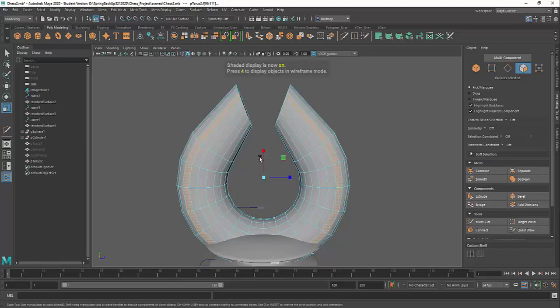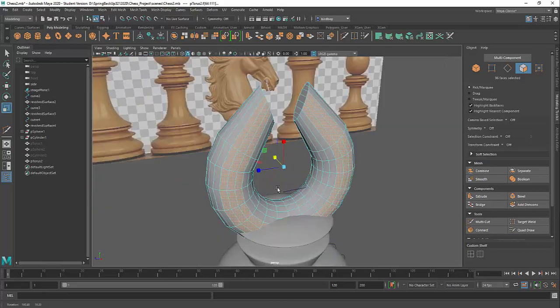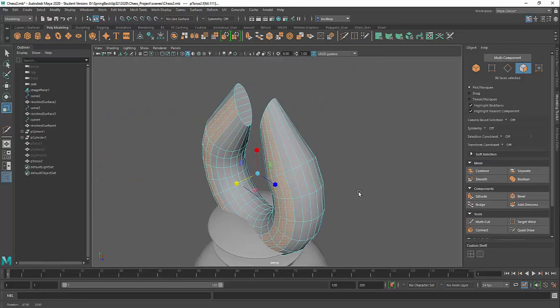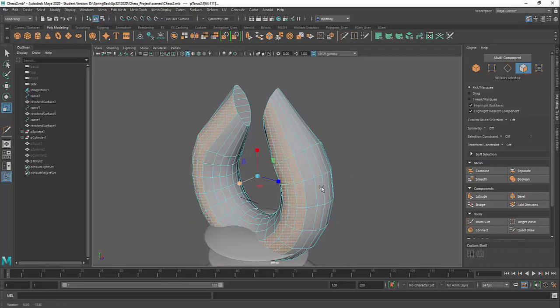and then it looks like I grabbed it. So if I go back to 5, you can see it there. So again, hold shift, click on this one, and then double click, and then shift click on this one and double click. It's an awesome way to select faces, you can select between the 2 loops. Now I can scale them out a little bit and kind of just give them a different kind of quality. So I thought it'd be kind of cool to scale that out a little bit.